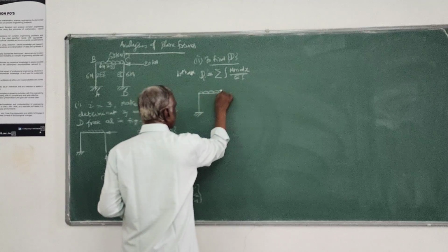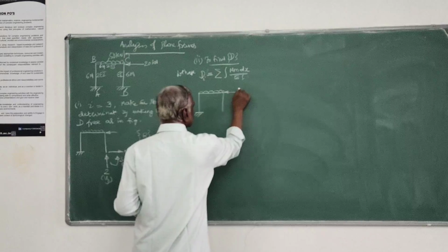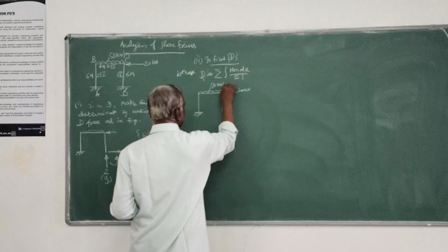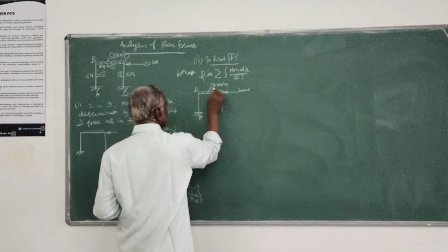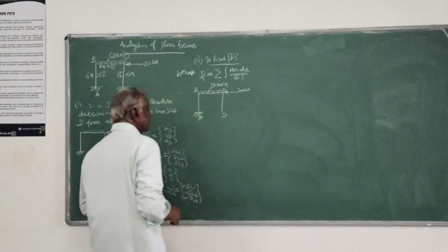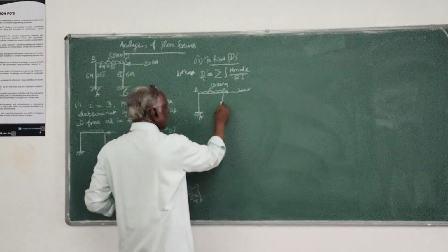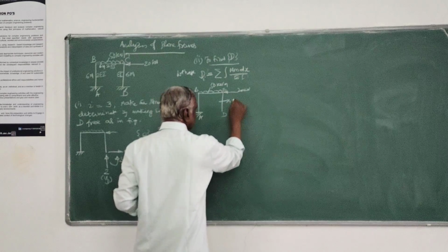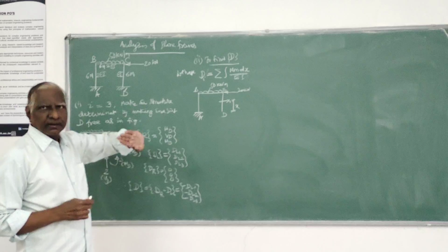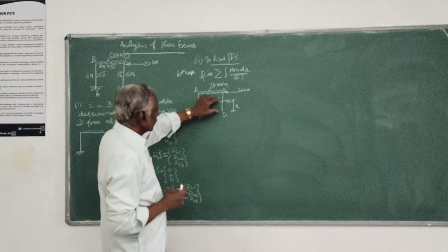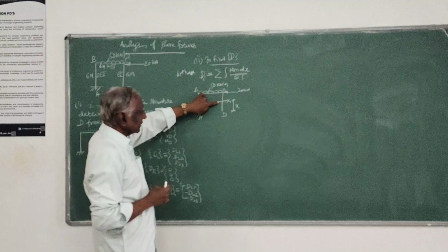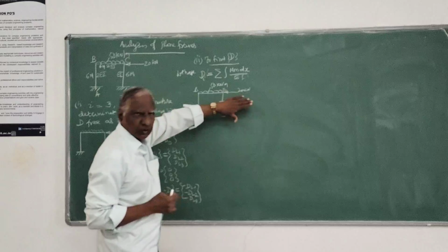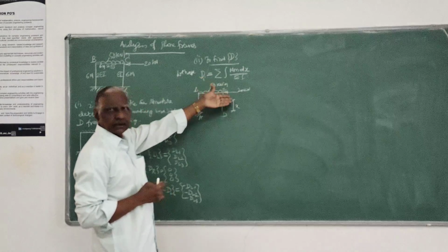The external loading is 20 kilonewtons and 50 kilonewtons per meter on A, B, C, D. In this member, I have to take a section x1 at a distance x from the lower point D. Whatever moment I take about this section holds good between D to C, because there is no other load causing variation of that moment.